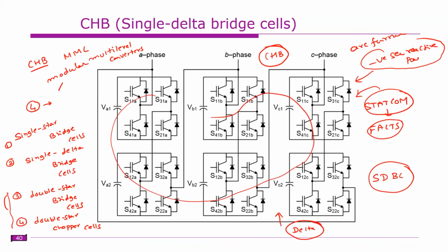You are aware of this, right? Zero sequence harmonics are circulated in the delta connection. Similarly, this negative sequence reactive power is also circulated in the delta connection. So the current that causes the negative sequence reactive power is circulating in this delta connection. Therefore, the source or the supply is free from this negative sequence reactive power.